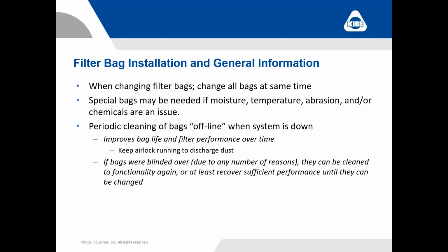So we'll talk about filter bag installation for just a second. I like to encourage people that when they change a filter bag, please change all of the bags at the same time. It doesn't do you a whole lot of good if you've got a set of bags that's been in the filter, even if it's a relatively short amount of time, 8 or 10 months, and one bag is torn or two bags are torn. Yes, it's quick, and yes, it's easy to go in and find those two bags and replace them, but you're not doing a whole lot for that baghouse.